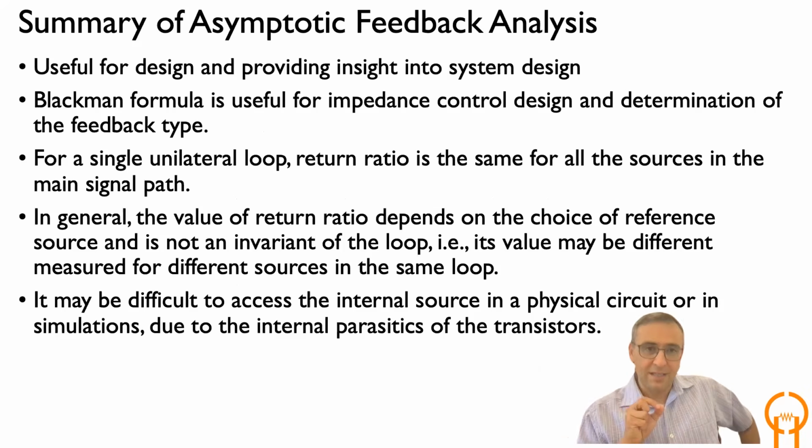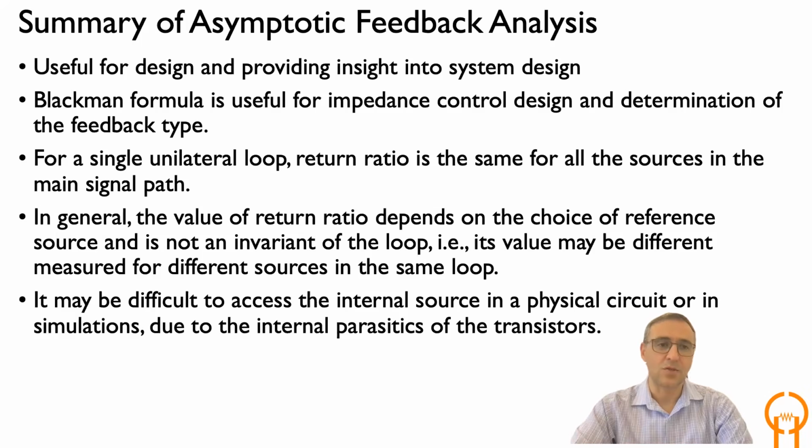So let's summarize the asymptotic feedback analysis. What is it? It is useful for calculation of the gain and it provides insight. It's a useful design tool because, especially with H infinity, you can have a very quick first pass design that would come close to what you need, and the return ratio will allow you to see how close you're going to be, in addition to H0. The Blackman formula is also useful for determining the input impedances as well as helping with design.